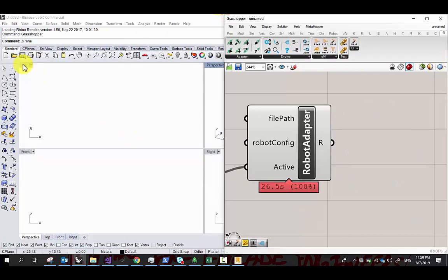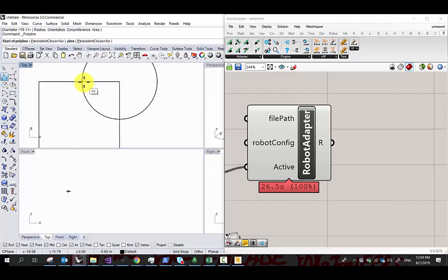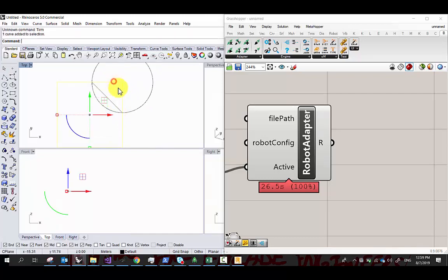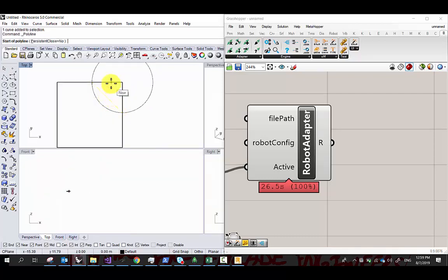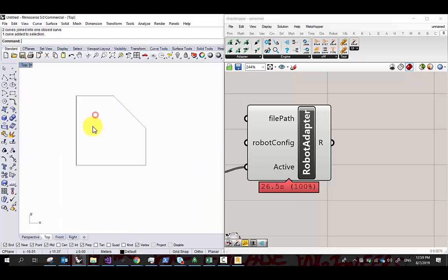So in this situation, let's just go over here. I'm going to create in Rhino. I'm in meters. You should always work in meters for the BHoM. I'm going to create a 1x1 rectangle here. And actually, I'm going to make it a little bit fancy. Let's see if we just chamfer it off here. Trim. You don't have to do this, but you need a closed thing that represents your glass. So that's our glass panel.